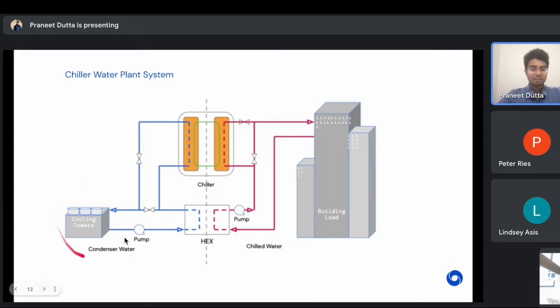So let's say it's a cold day outside, again like 48 degrees, and this requirement here is from 55 to 45. The leaving temperatures at both ends, so here and here, would be close to a midpoint. That would, of course, depend on other factors. This is a simplifying assumption, since it would depend on how fast the water is flowing in one pipe versus the other. But let's assume it's all equal. We would see gradual equalization. So this pipe here would be able to directly cool this down to a lower level.